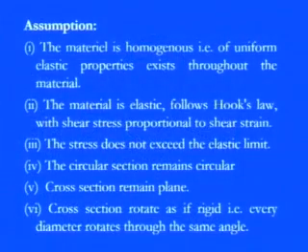This is one. And the fifth assumption is that the cross section remains plane, because if it is not planar, then the stress distribution within the total cross-sectional area of the circular shaft will not remain the same. And you would see stress concentration or other phenomena and properties that are altogether different.